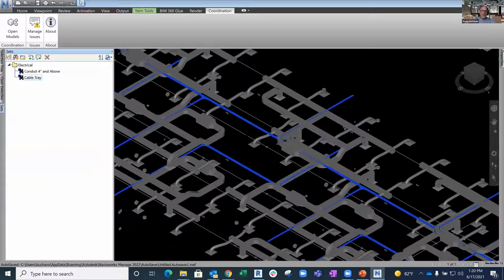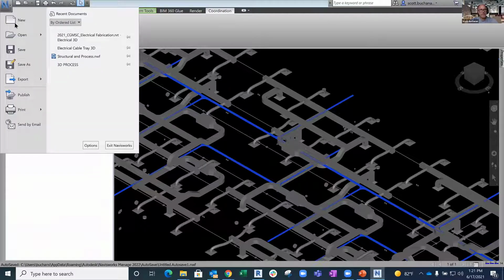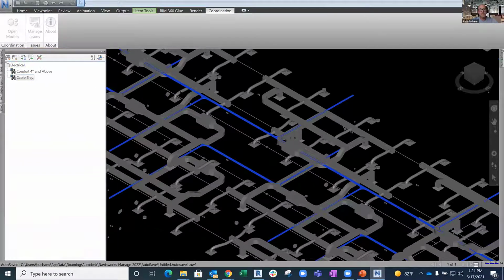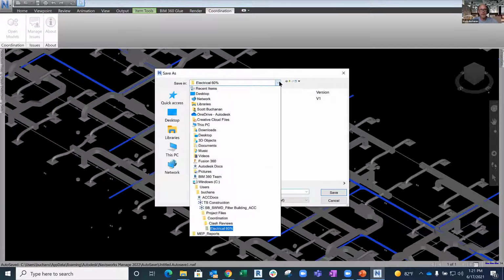Now, if you run clashes here, there's nothing that pushes those clashes back to our cloud, BIM360, Navisworks. It's just that communication of issues back and forth. But if we save this as an NWF file, which is your normal type of practice, save it inside of BIM360, it remembers that coordination space behavior, right? So if the Revit model were to get uploaded and have those changes fixed, I'm in a completely different project, but I'd go save that NWF file. If they fix the cable tray for real, and not just say it, move it up, make that change.